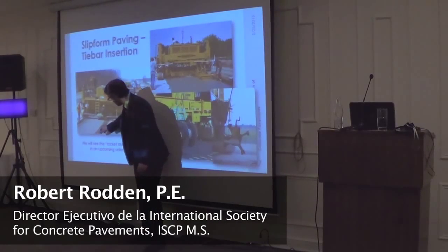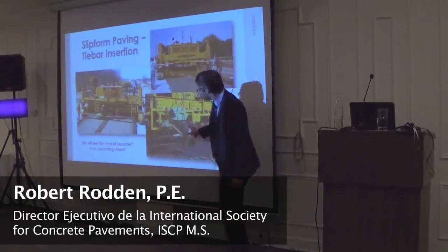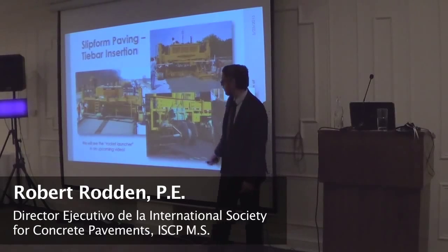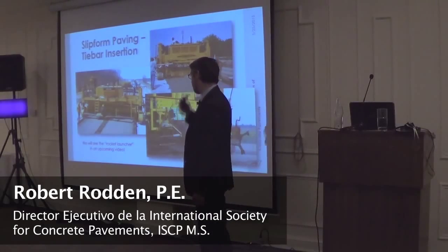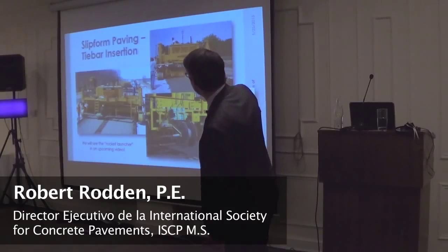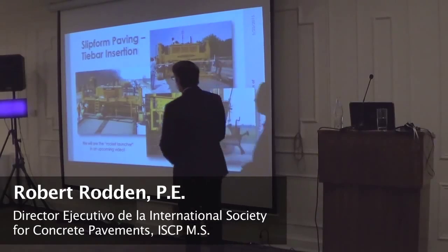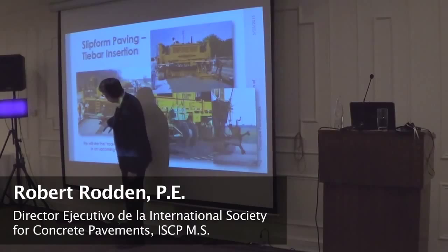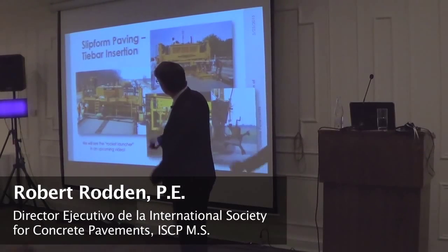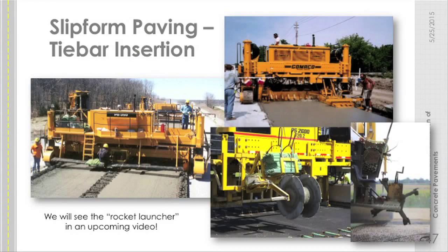Here's the end result of this device dragging through the fresh concrete. So it's roughened up the surface some. It's not really that bad. That can be closed off in the finishing operations. It looks like here, yeah, that is happening right before finishing, it appears. No, this might be during a placer spreader. I don't know what that piece is. Yeah, that is a placer spreader, 350. So that's happening before it's even going through the slip form mold.